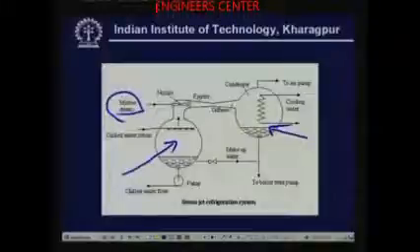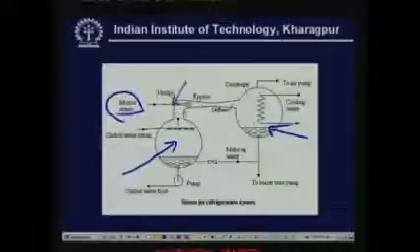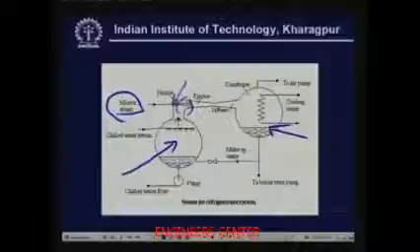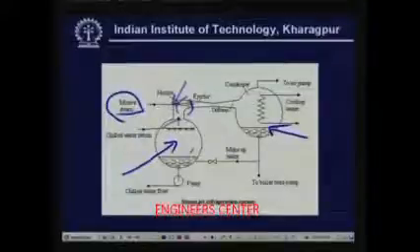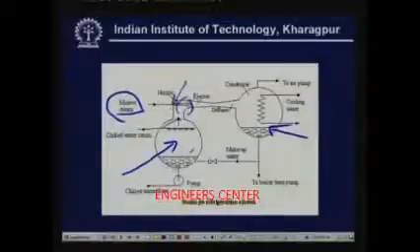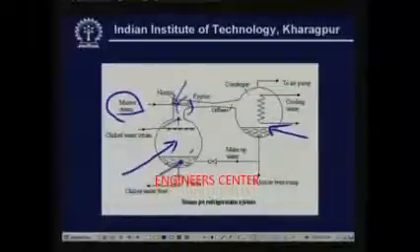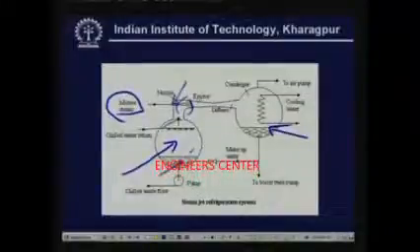So when this high pressure steam flows through this nozzle, its pressure reduces and it gains kinetic energy. That means at the exit of the nozzle you have a fast moving motive steam. So because of its high velocity, it can entrain the vapor from this drum. That means whatever vapor is there in this drum gets entrained by this fast moving motive steam, right. So vapor is removed from this drum. So once the vapor is removed, more vapor is formed by evaporation of the remaining water. That means the water evaporates to provide the continuous vapor. So as a result, the rest of the water gets cooled because evaporation is endothermic. So you have production of cold water here.